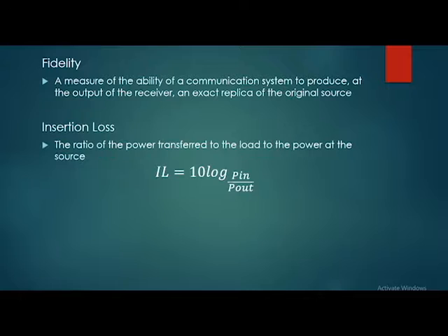Fidelity is a measure of the ability of a communication system to produce at the output of the receiver an exact replica of the original source information. Insertion loss. Insertion loss is the ratio of power transferred to the load to the power at the source. Given the formula IL is equal to 10 log of power in divided by power out.